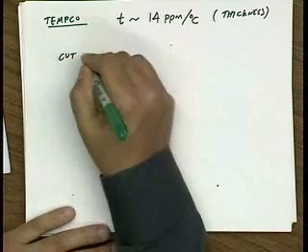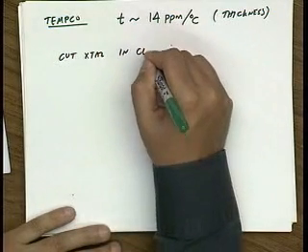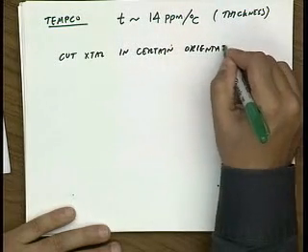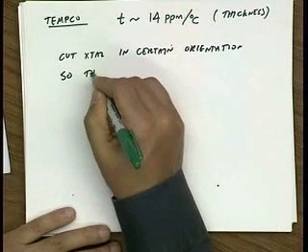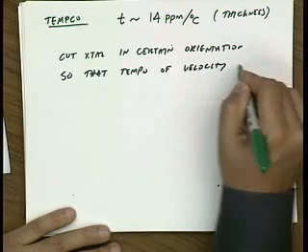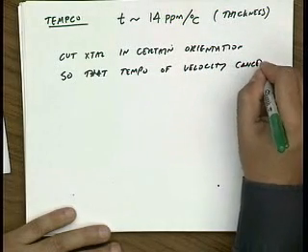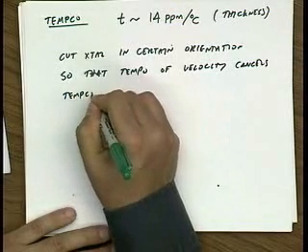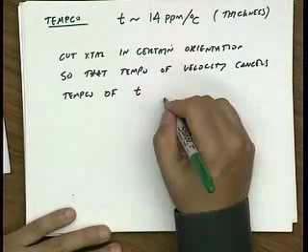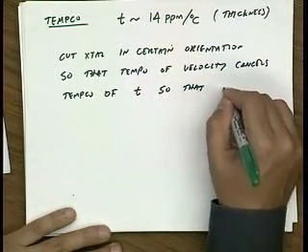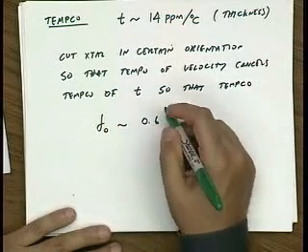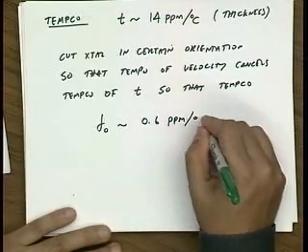So if you cut the crystal in a certain crystal orientation, you can cancel out the temperature coefficient of the phase velocity with the temperature coefficient of the thickness, so that overall, it's not a perfect cancellation, but your frequency stability becomes about 0.6 parts per million per degree C.